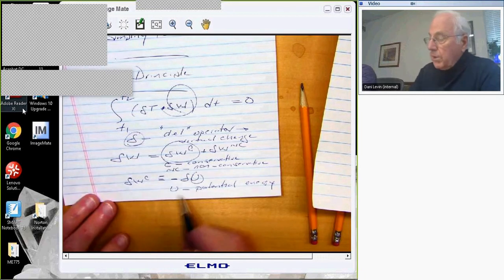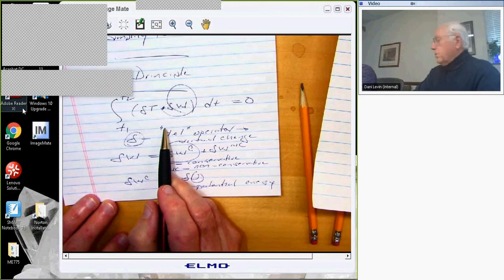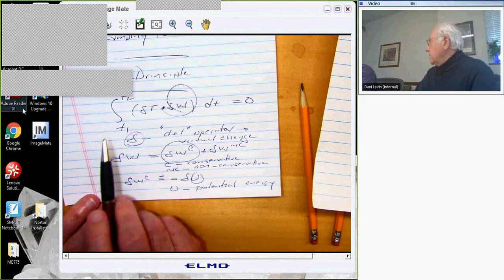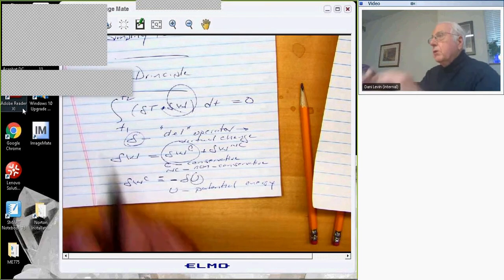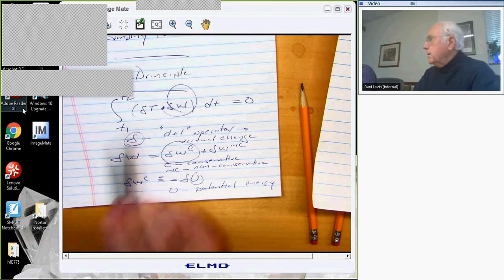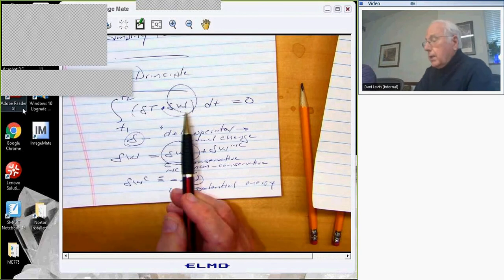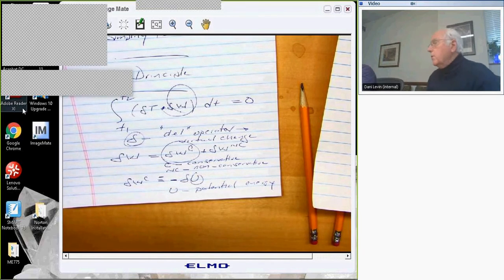And so if we do this, then apropos to your question, this is del T now minus del U plus del W in C. So del U is going to come from some structural model. Del T is going to come from knowing the kinetic energy of the structural model usually. And del W and C is going to come from knowing something about aerodynamics. Chapter 4 is entirely devoted to aerodynamics. If you will, it's entirely devoted to computing del W and C. Okay. So that's why we want to know Hamilton's expression.